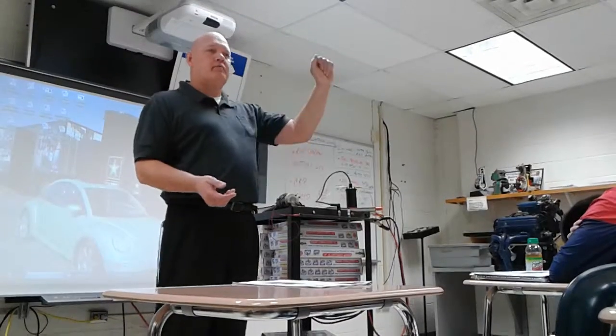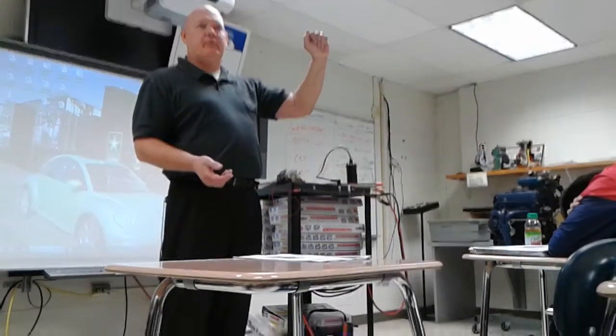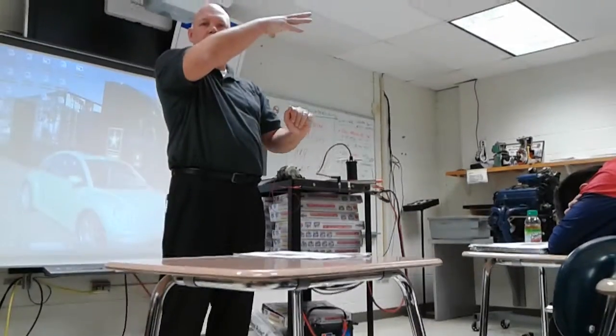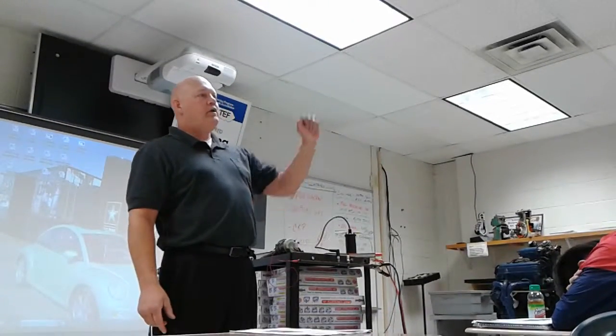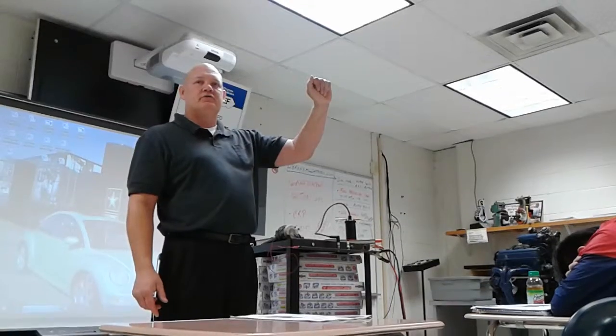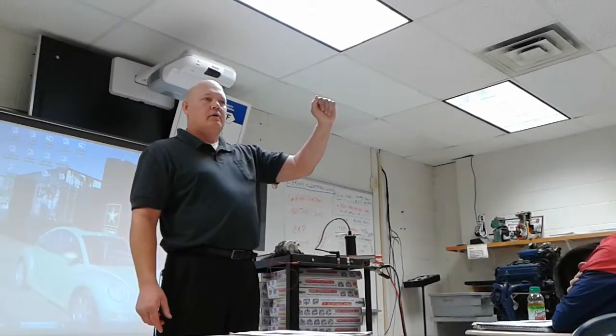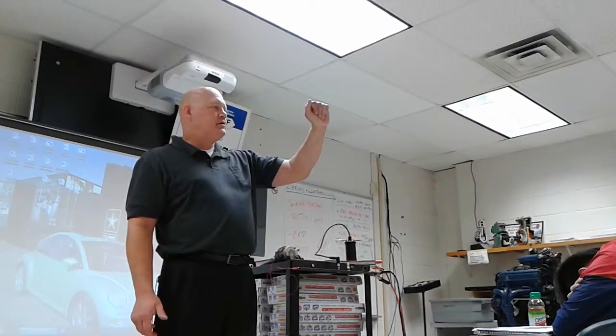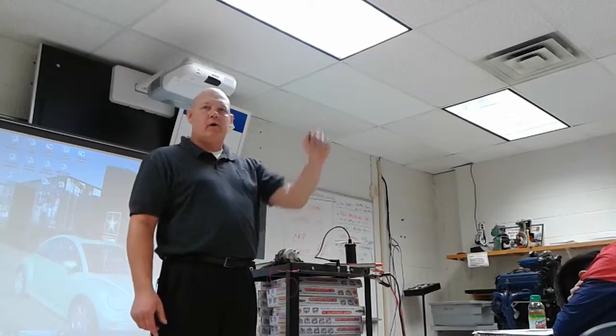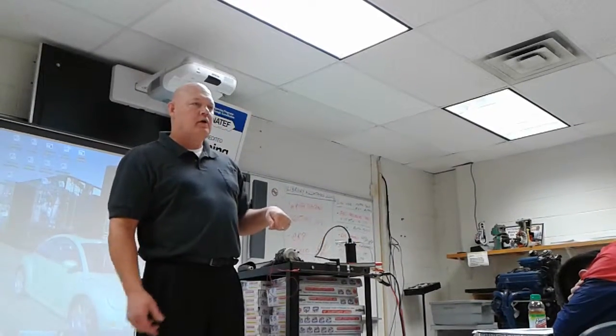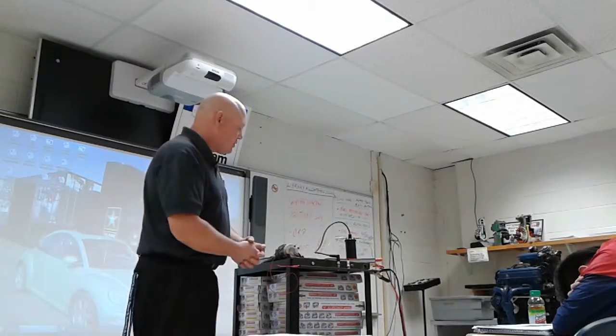We got intake, now we have compression. Now we want that spark to happen because the next stroke is power. We get the power stroke because the air and the fuel is burning to push that down, right? So once we get to top dead center, the compression stroke is done, which everybody calls top dead center compression. Now we want power. Now we want that spark to happen, okay? So something's got to time it to happen at the right time, and no human could ever physically do this over and over again. So they use a device.